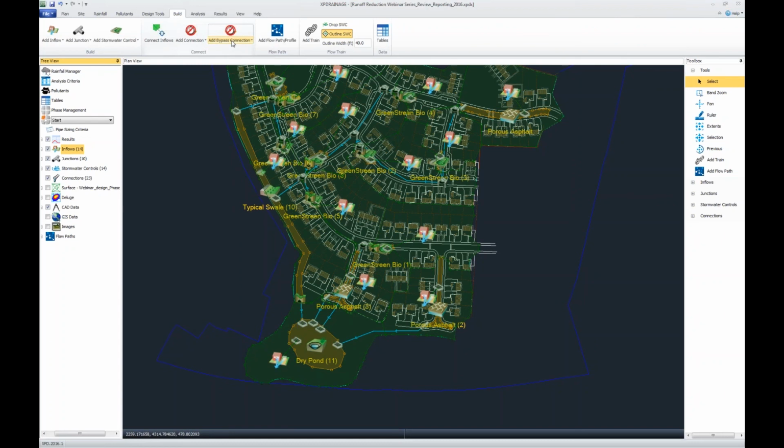And if you see your system flooding, there are indicators in the plan view, indicators in the profile, and all the report summaries will show you if you've exceeded your capacity. All that's going to identify perhaps you need to upsize your outlet, perhaps you need to implement some sort of system of bypasses.